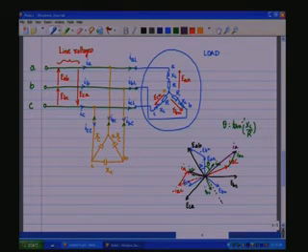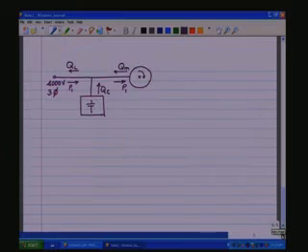Now, if we adjust the values of the capacitive reactances here such that the IAC currents are adjusted, then one can adjust it to the extent that IA just about manages to be in line with EAB. Then you have unity power factor as far as the lines are concerned, from the line side. So, that would be the function of the capacitance C. Of course, with the numerical example it will become clear.